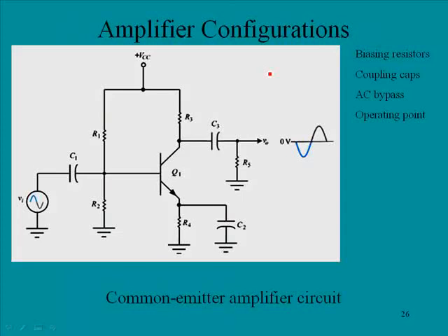Okay, here we have the common emitter amplifier. The reason that it's called a common emitter amplifier is that for purposes of AC, the emitter is the point where the AC signal goes to ground, hence the term common, meaning ground. The emitter is the ground for AC, and so the signal source here is our AC signal source that comes in, and then the ground is actually through this capacitor. Remember that a capacitor is a ground for AC and an open for DC. So signal source goes in like this, and since the AC is grounded through the emitter, hence we have the term common emitter.